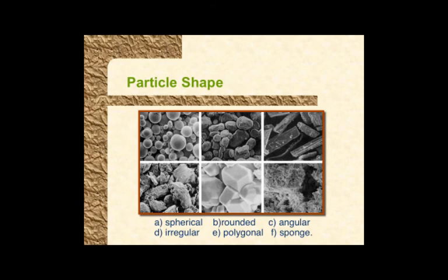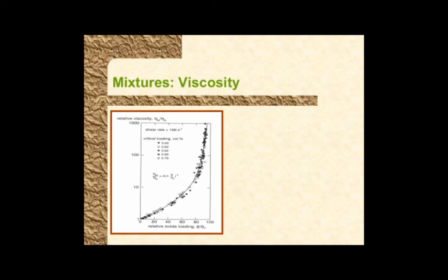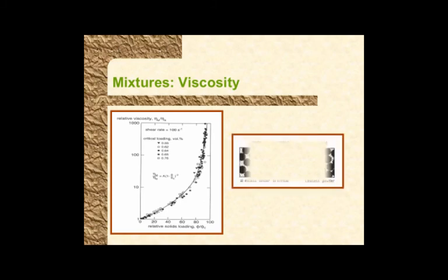So to connect the context of mixing to the starting materials, we have to first deal with the fact that you have different materials, shapes and sizes, different packing fractions, right? Different viscosities. Right? And so how much powder you can mix is affected by this packing fraction, which depends on particle size. That's one thing that we looked at. And so if you operate in this region, it's going to be harder to get a good mixture.